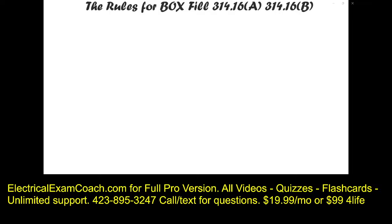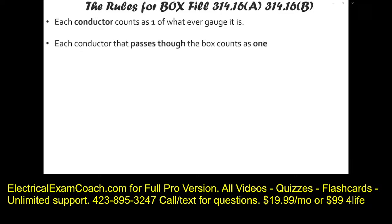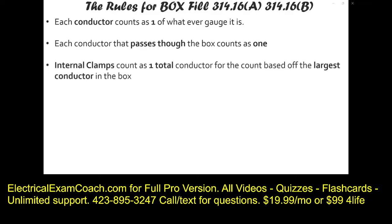We're going to calculate those separately at the end of this slide. So now we're dealing with only neutrals and hots. Each conductor counts as 1 of whatever gauge it is. So each 12 counts as 1. Each 10 counts as 1, whatever gauge wire it is. Each conductor that passes through the box counts as 1. So even if it doesn't terminate or splice inside that box, if it's passing through that box, it counts as 1 each. Each internal clamp only counts as 1 total based off the largest conductor that's in the box.